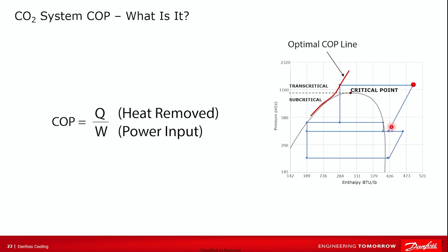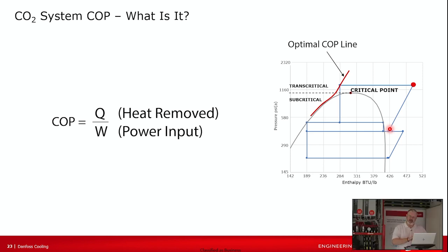The pack controller is performing that calculation on an ongoing basis. So it knows the displacement of all the compressors. It knows how many compressors are active. It knows the ambient temperature. It knows the pressure leaving the gas cooler. And it works to keep the temperature exiting the gas cooler on this line because it knows as long as that is happening, we're using just the amount of energy necessary to do this work. And that's all you want. There's really not a way to use less per se, but we want to use just the energy required.